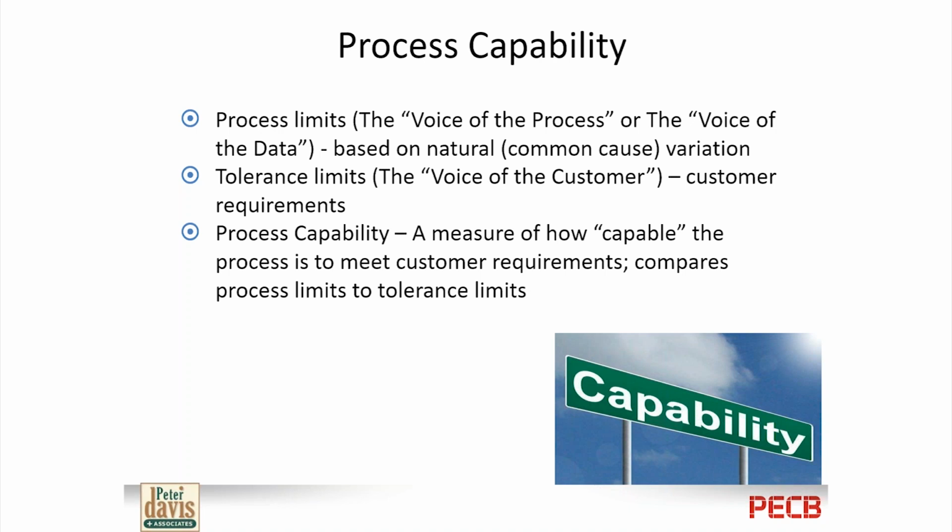Perhaps some of you have heard of ISO 13053-1. It describes a methodology for business improvements known as Six Sigma. ISO 13053-2 specifies tools and techniques. In there, you will find CP and CPK, which are basically process capability indices. This definition that we see on this slide here is basically CP. If you're into calculating CP and CPK, I will show you very quickly how it fits into what I'm talking about today.